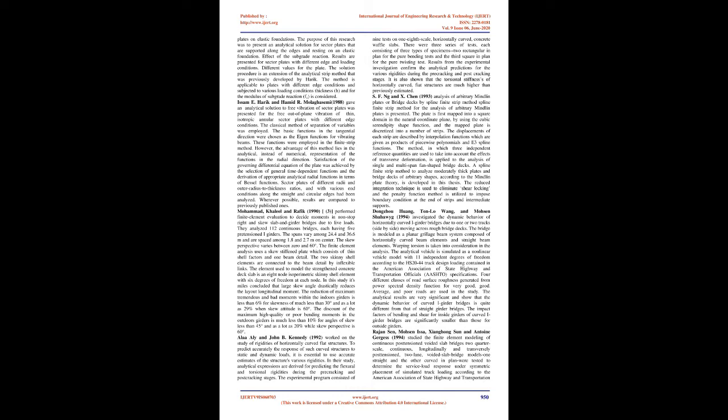Mohammed, Khalil, and Rafiq, 1990, performed finite element evaluation to determine moments in continuous right and skew slab and girder bridges due to live loads. They analyzed 112 continuous bridges, each having 5 prestressed girders. The spans vary between 24.4 and 36.6 m and are spaced between 1.8 and 2.7 m on center. The skew angle varies between 0 and 60 degrees.